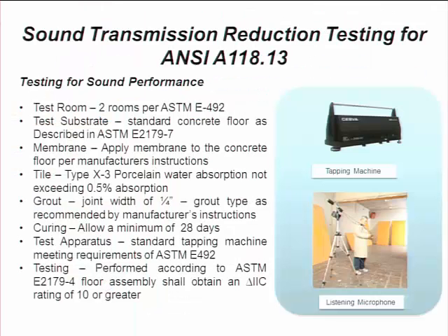Looking at the sound transmission and testing, the ANSI 118.3, if we get into a little detail in reference to that component of the test, that's where Robert from NGC will have more in-depth knowledge in reference to the particular equipment because they do the actual testing. But from a test perspective, you're looking at two rooms. You're looking at the room above and the room below. In the room above, you would be putting the tapping machine on there, and then you would be measuring the value in the room below.